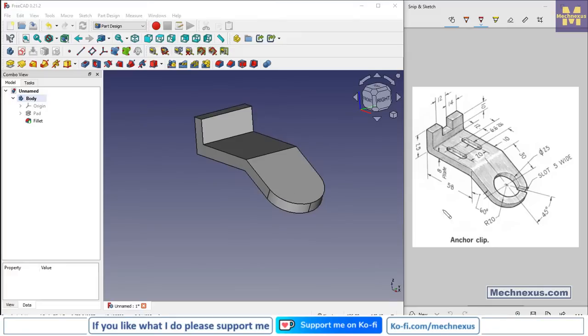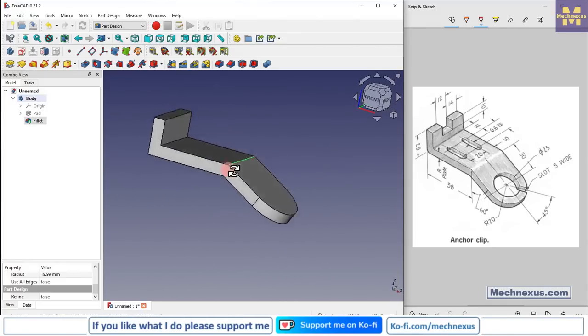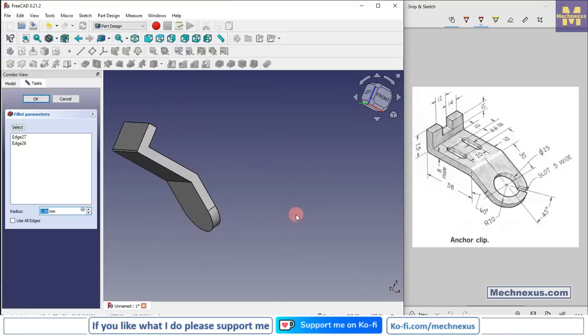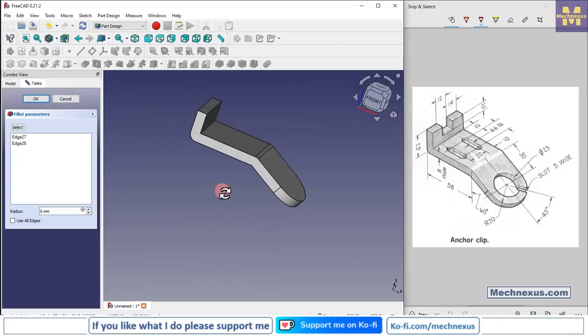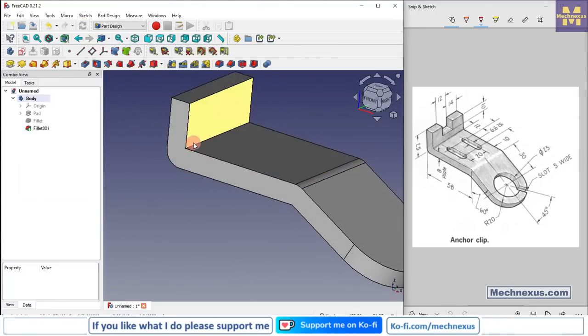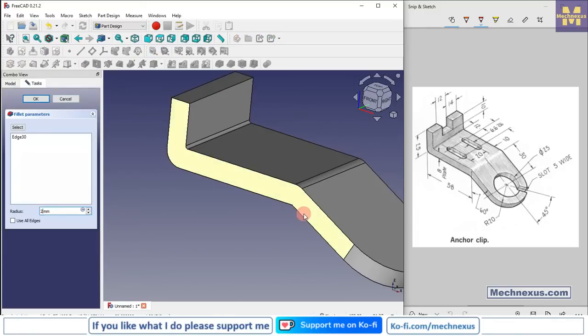And now we will add the fillet to these two edges. So press the control key and select these two edges and click on the fillet and provide the value of 6 mm. Click on OK, and here we will provide the fillet of 2 mm. So select the edge and click on the fillet, give it 2 mm, say OK.